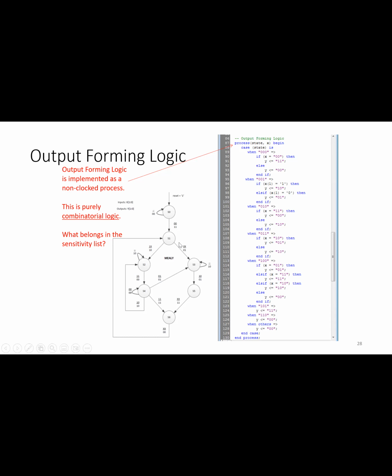As you can see in the diagram here, I am in this present state. I can have output 0, 1, depending on the input. And from the same state, I can have output 1, 0, depending on the input. So in this Mealy machine, output depends on state and input. Have you written that down, Paige? Yes, I have. So what is the difference between Mealy and Moore?